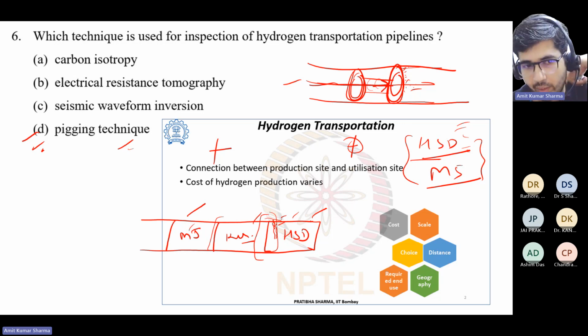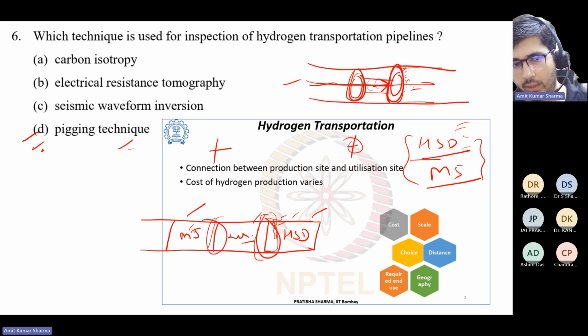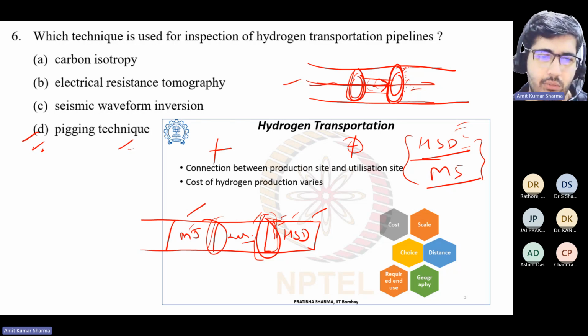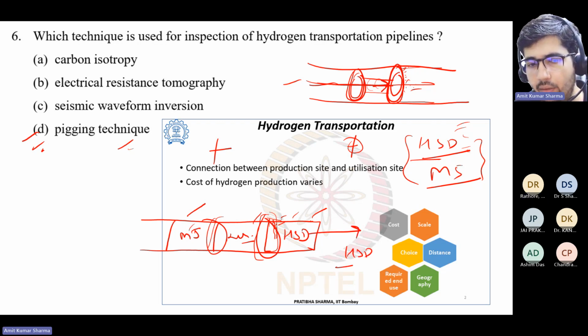Actually this is a very important part, called interface handling. It is a very important part of the oil industry whenever you are in pipeline operation. If you don't switch at the right time, suppose currently my flow is going into the HSD tank. In this tank I need only pure diesel. I don't want the mix of kerosene also. I have three tanks.